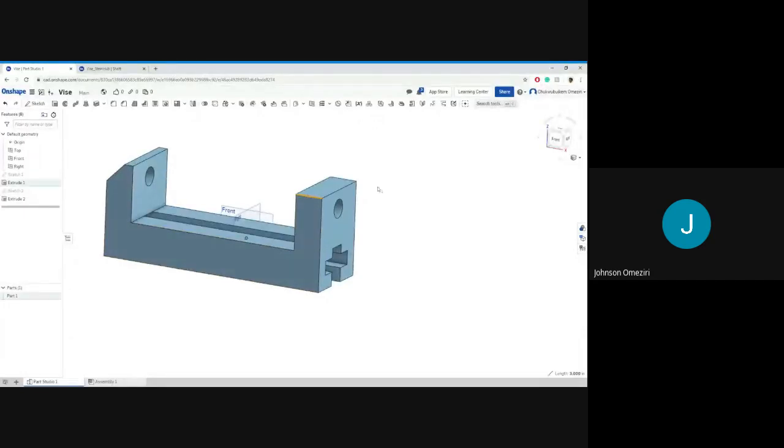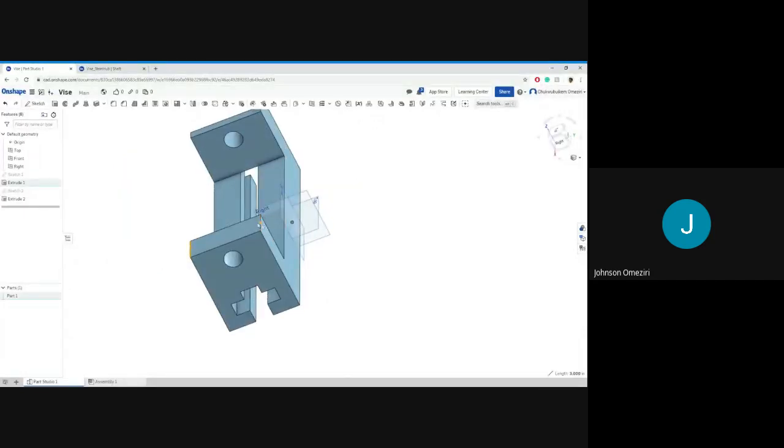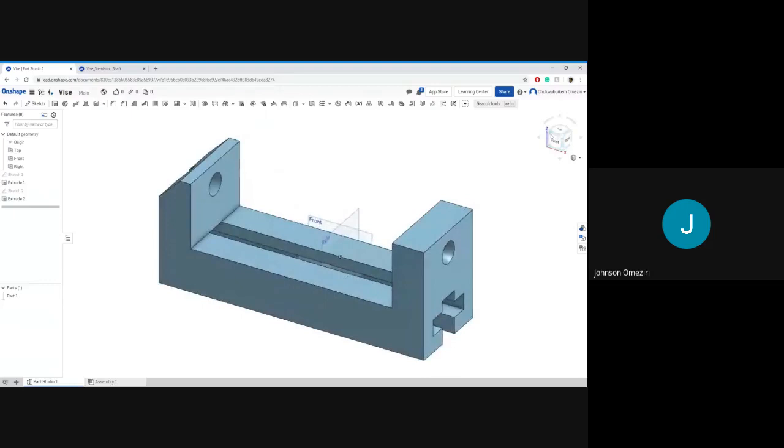Okay, so we click on this edge here, or we could just first click here, the top side. Let me slowly use the orientation cube here to position it like this so you can see. The orientation cube is over here. Click on this dot here in the orientation cube. Then once you have it in this position, you can click on this top edge here.